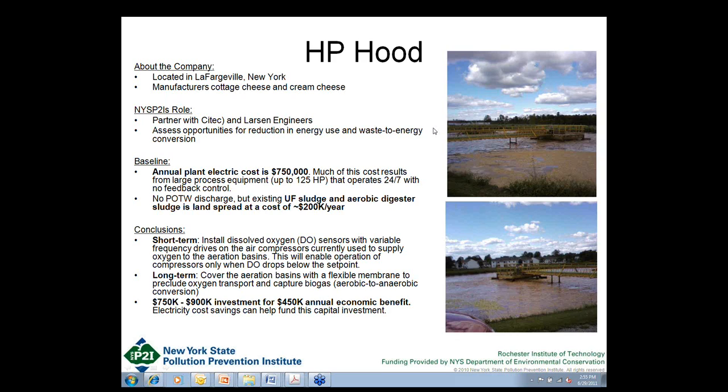So again, in this case, it was an opportunity to convert them from using aerobic digestion to anaerobic digestion, which, if you look at the very bottom bullet, for about a $750 to $900K investment, which is significant, they would be able to save about $450K annually. And so really the payback is 2 years.